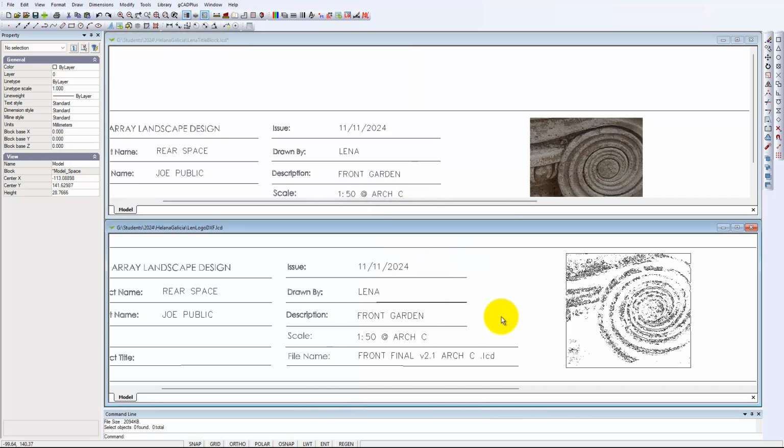If we come down to the lower one, where I've succumbed to the temptation to take the raster image that works in the CAD software, although this is vector. It can accommodate raster images, but I've thought, let's turn this one. There are services on the net that can turn raster images into vector, and therefore the drawing at the bottom here, the title block, is all vector.